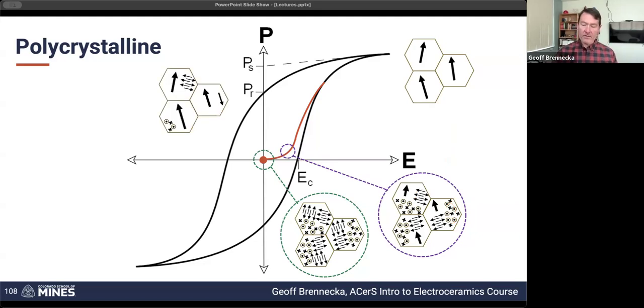to minimize the overall surface energy, the overall energy, and the strain that has developed by switching those 90-degree domain walls, some of these domains are actually going to switch back. So this one used to be pointed in that direction, and now it's gone through a 90-degree switch.